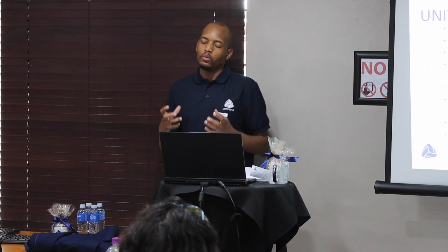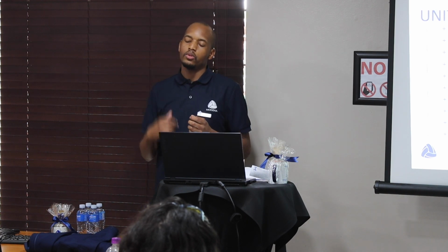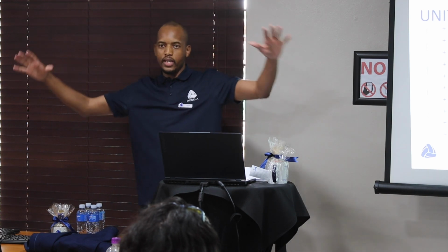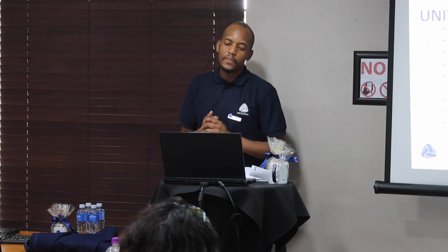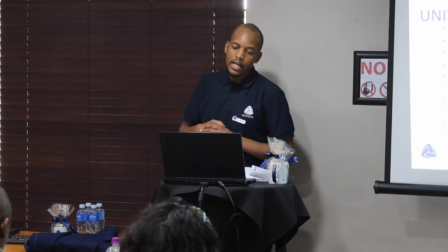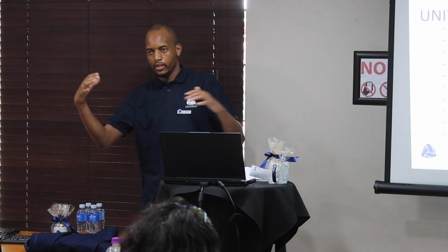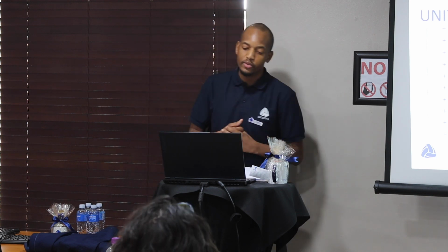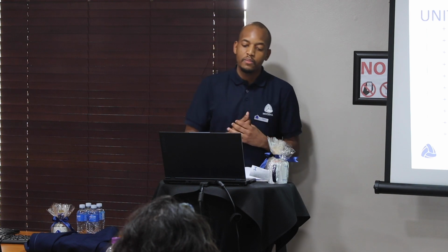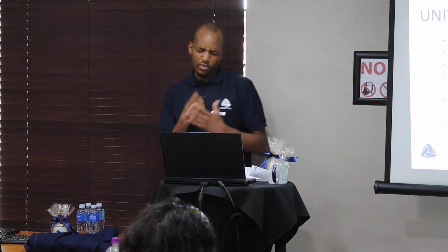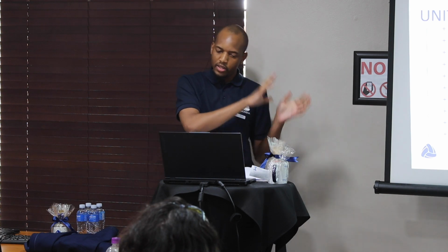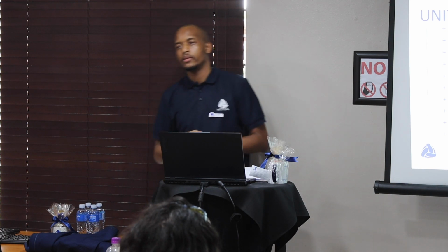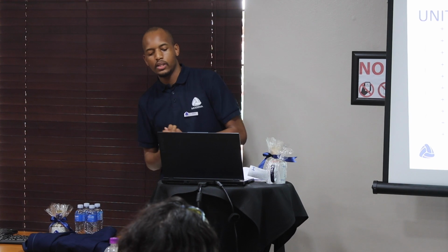So if you're using it with your computer, you can actually go into the virtual reality environment and see how all those changes look inside your virtual reality. And one of the biggest benefits of using Unity Reflect is that it shows all the BIM information. You are able to view all the BIM information in Unity Reflect, and it maintains a live link to your original Revit model. So all the changes that you make in Revit will automatically sync to everyone who's downloaded the Unity Reflect application, and you can communicate and do all this.